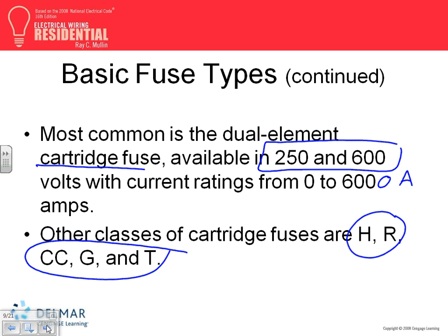For the most part, guys, at least in the power industry, engineering-wise, you're either dealing with non-coordinated fuses on feeders, dual element coordinated fuses in circuit breakers, or current limiting fuses. And the only time you buy a current limiting fuse is if your equipment is not rated to handle the available short circuit. It's the only time you use a current limiting fuse.